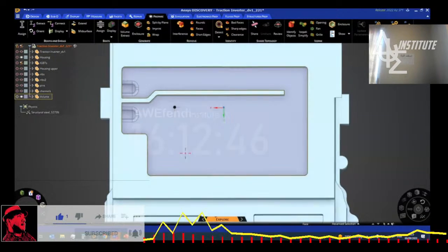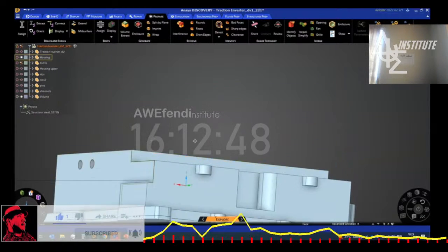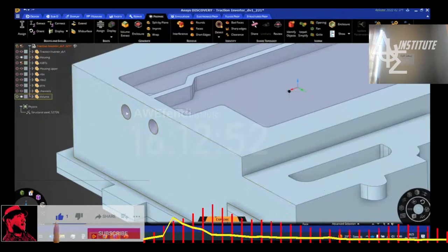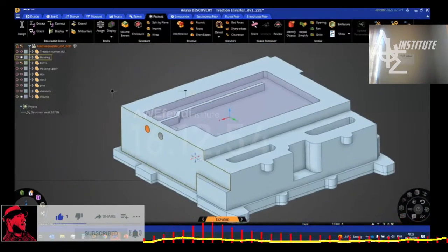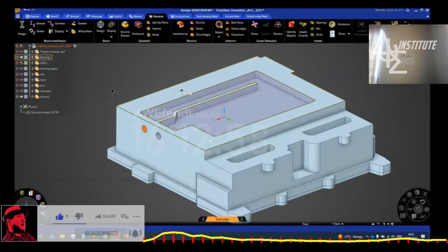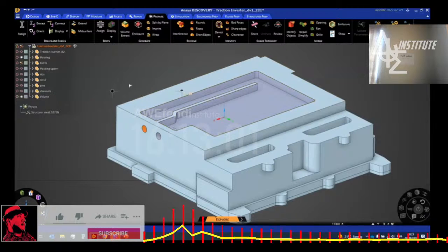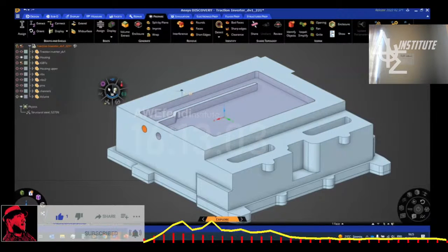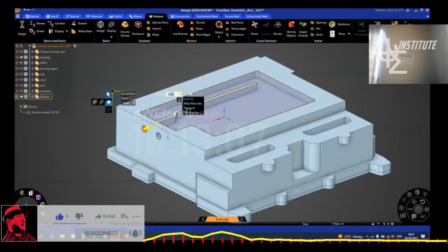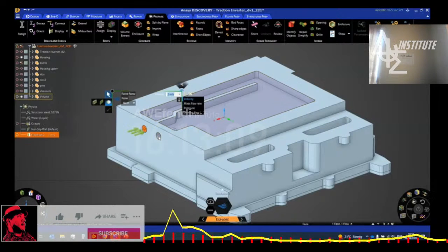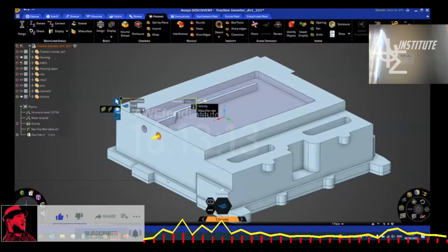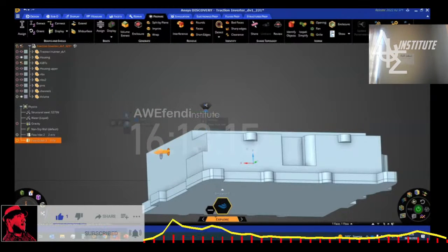And so we just want to see which one behaves the best in terms of recirculation zones and pressure drop. If you have too many recirculation zones, those are areas where you're losing potential energy from the flow to extract heat from your system. So you want to avoid those if possible. So, just visually, we're going to look at where those are and which design variation looks the best. So let me set up the fluid flow, then we can look at it from the top.